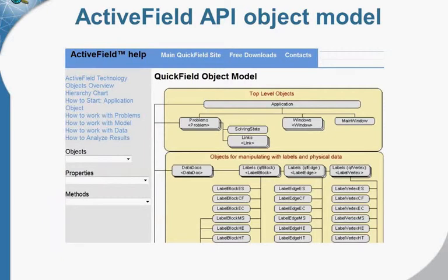For this webinar, we have prepared a trajectory calculating script written in Excel Visual Basic, which performs numerical integration of the equations of Newtonian mechanics using the local electrostatic or magnetic fields derived from the QuickField simulation problem. You may use the script as is or modify it or write your own procedure from scratch following our example. Now my colleague Alex will demonstrate how to calculate charged particle trajectory using QuickField Electrostatic Postprocessor, and then he will show you our free open source tool for 3D trajectories in 2D electrostatic or magnetic field simulated by QuickField.